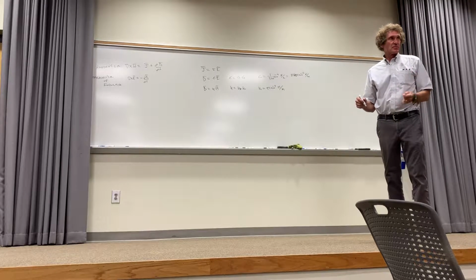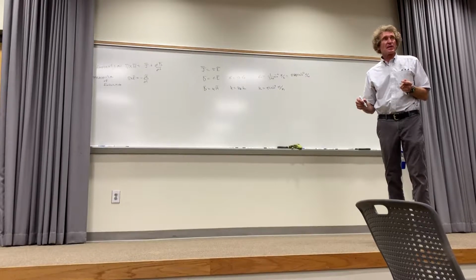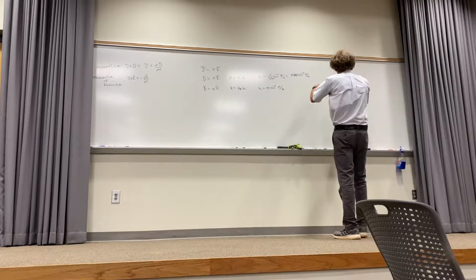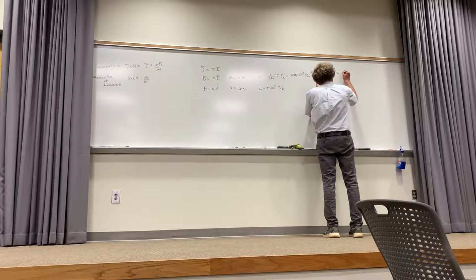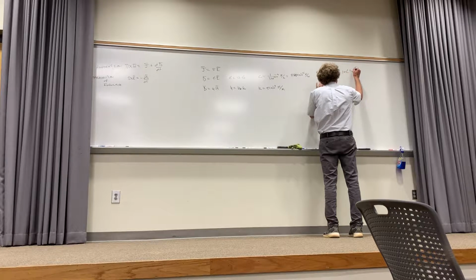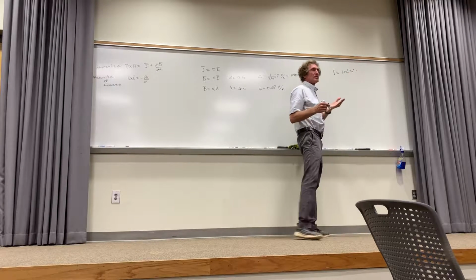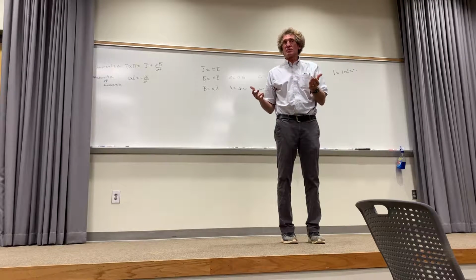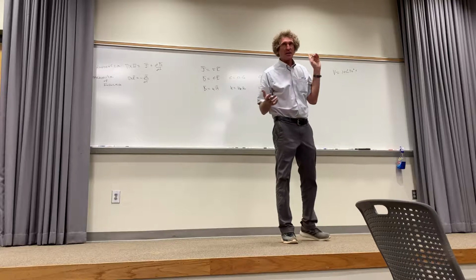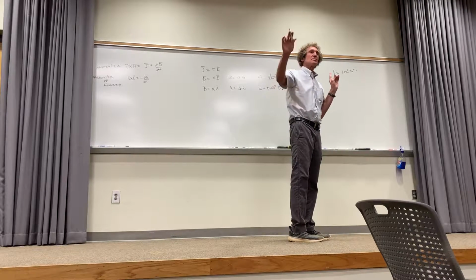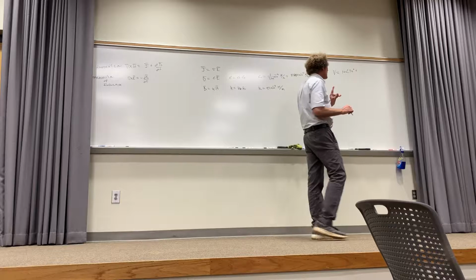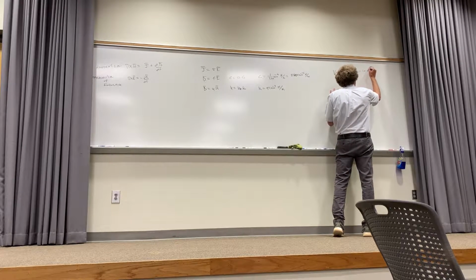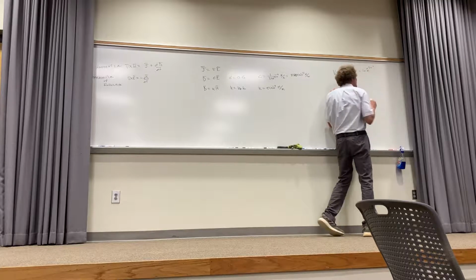You've had phasors, right? You've used phasors extensively, either in your circuits course or somewhat in EMAG. Back in the day, if I say I have a voltage of 10 at an angle of 30 degrees volts, that's something you can liken to a source. What's not stated there is the frequency. Do you follow me? This is a phasor identity. It completely extinguishes the e to the j omega t term. Now, I can also write it as 10 times e to the j 30 degrees. You all agree with that?